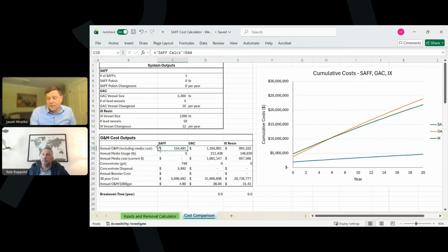So it does factor in how dirty your matrix is and how often you need to clean the system. Your SAFF costs include cleaning the system, weekly inspections and maintenance, the media usage, electric usage, and any foaming additives. Whereas your carbon resin costs include a weekly inspection and disposal of the media. And if there are electric costs for those, they're very low, so they're almost insignificant.